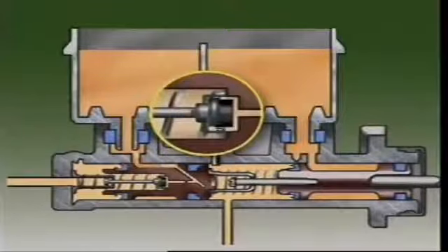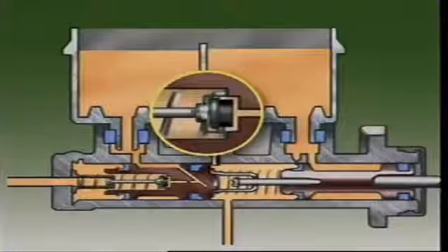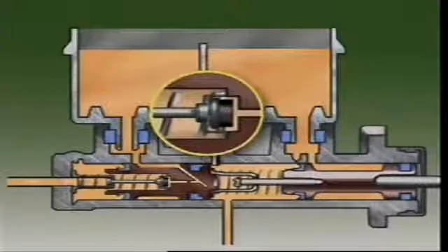Any difference in pressure lifts the center valve from its seat and lets fluid enter the chamber ahead of the secondary seal and prevents low pressures developing. When the piston has returned to the rest position, the seal is pulled off its seat by the action of the link and spring. This lets fluid still returning from the wheel units displace fluid back to the reservoir.